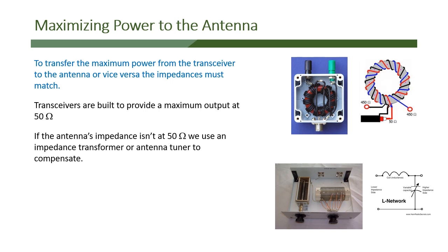Below that, we see a circuit, which is an inductor and a variable capacitor. We can tap the inductor at different places because of different band needs that we want. What we do is vary the capacitance, or vary the position of the coil through these taps on that switch, and what we're doing is an impedance transformation. You can do an impedance transformation like you do above with some wire across a toroid, or we can use variable inductors and variable capacitance to adjust and do the impedance transformation to match the transmission line to the antenna.